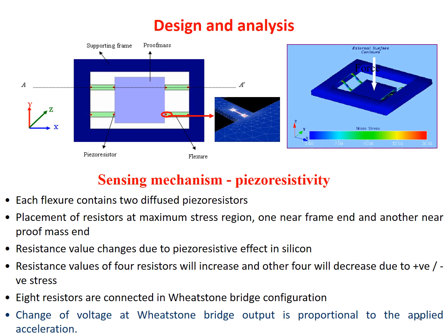And if we zoom into that portion, this zoomed portion has been shown over here, where this is my piezoresistor, you can see, right. So this is that straight line, and on both sides we have bond pads to take the electrical connection. So this is the piezoresistor deposited both towards the mass side as well as the frame side, fine.